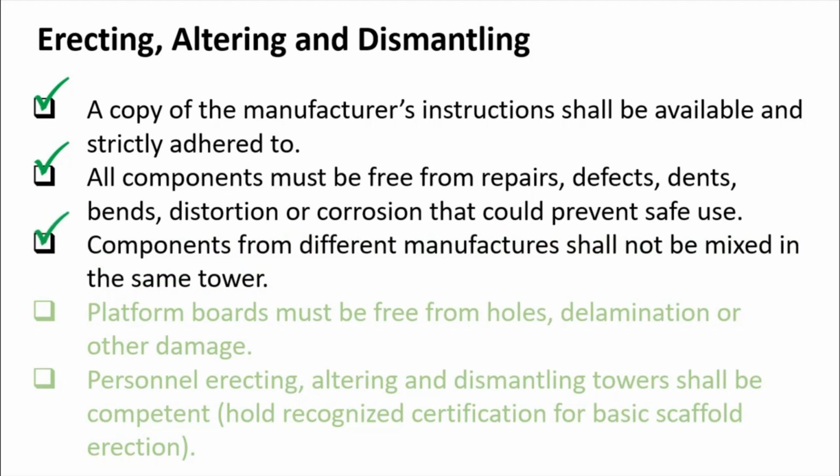Components from different manufacturers shall not be mixed in the same tower. For example, you have one whole scaffold of one manufacturer, and then you have missing bracing.